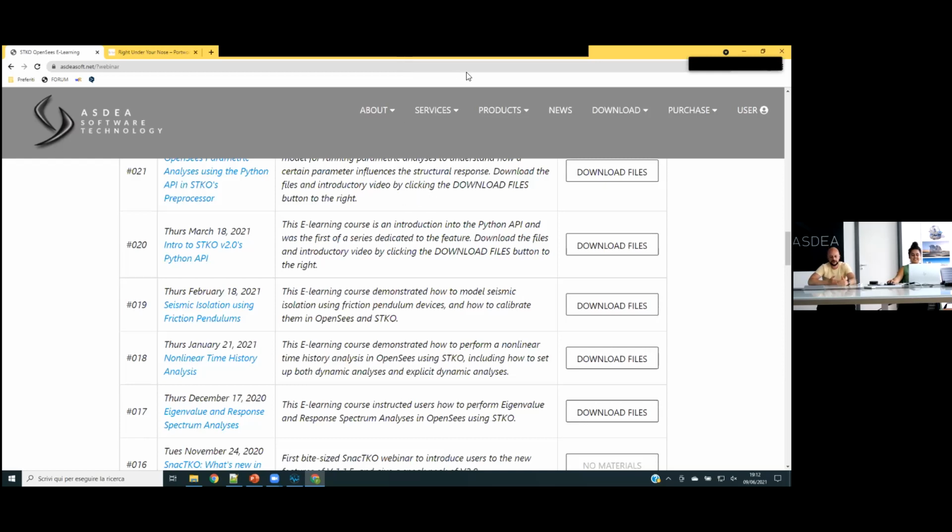Basically, there is a custom Tcl command that defines the application points of the train and of the van of the train. The user can specify the distances between the wheels and the total duration. For example, the load enters the bridge at a certain time and exits at another time. We also showed how to move the mass of the train for a dynamic analysis. You can use the same concept to take the current displacement of a shell, recompute the normal and apply the load. So remove the previous load and apply a new load, which is normal to the surface of the shell.